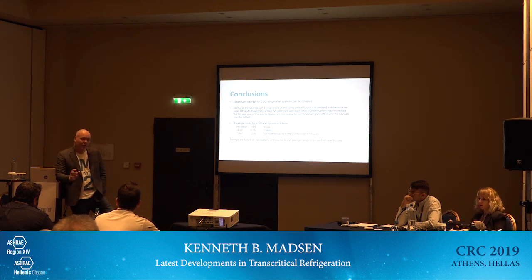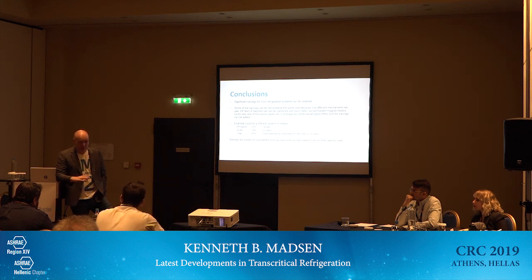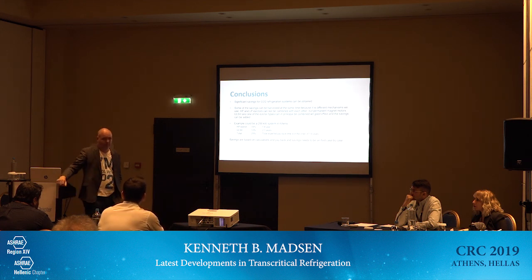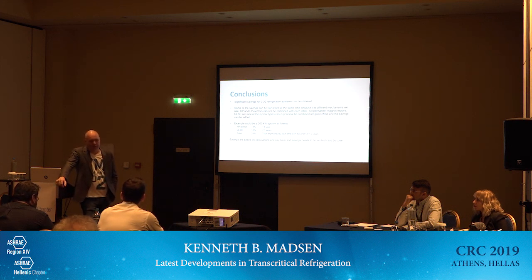And then we can see we get very, very close to ammonia if you include the brine system on the cold side. But on a one-to-one comparison, ammonia is better. If we have flooded systems or whatever, then ammonia is just a fantastic refrigerant.